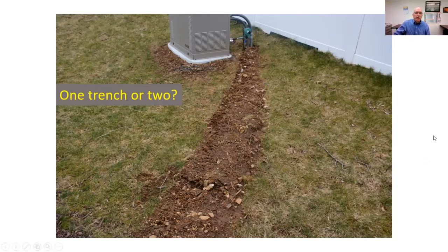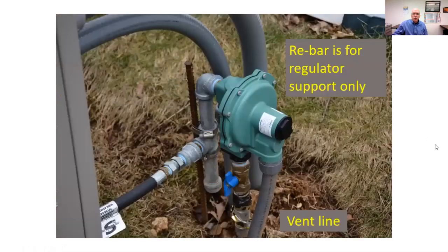That is for certain. But your electric utilities, like the electric utilities in our area, when they take a trench to a house, they'll put the natural gas line and the electric lines in the same trench. Again, they have their separation. The utility has their own rules for separation. And then the plumbing and the water, they go into a different trench. So the utility puts the fuel and the gas, as well as the electric, in the same trench. So we could do the same thing, but pay attention to your separation rules.